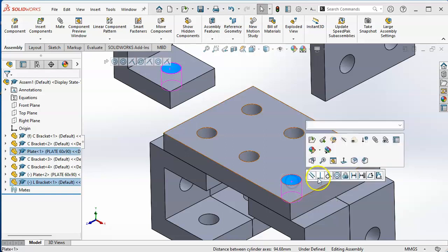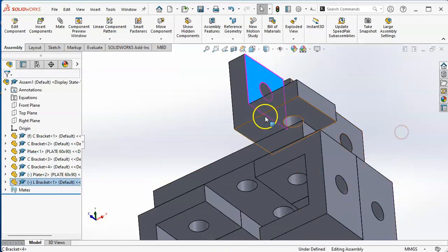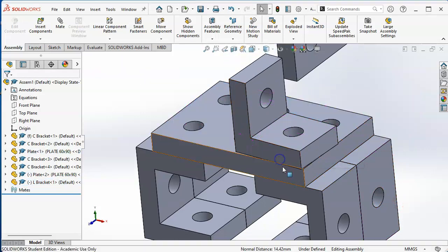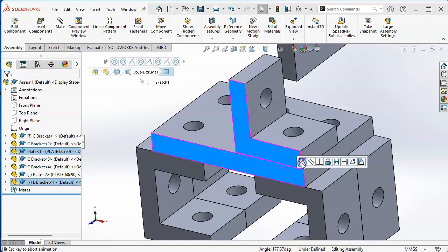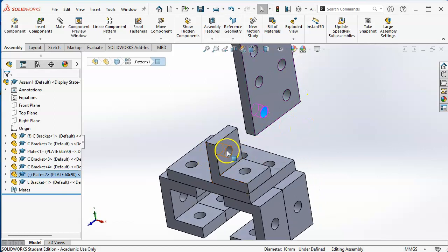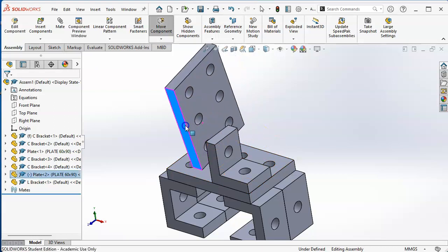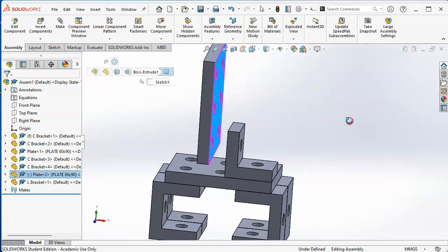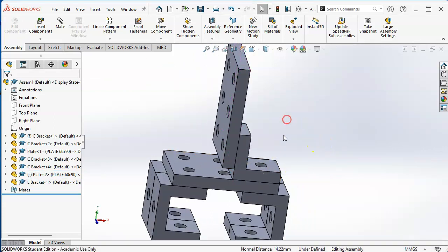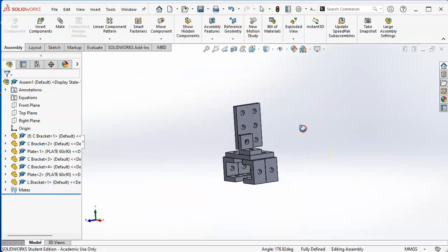All right, so select, control select. I'm going to slip back into my habit, and we'll go coincident. All right, so just rotating over, middle mouse wheel, select, control select. If you miss, just pick again. All right, now that one's in place, so I can see both of those in that view. Concentric, little rotation, and now we'll start to see what I was looking at in the difference from their model.